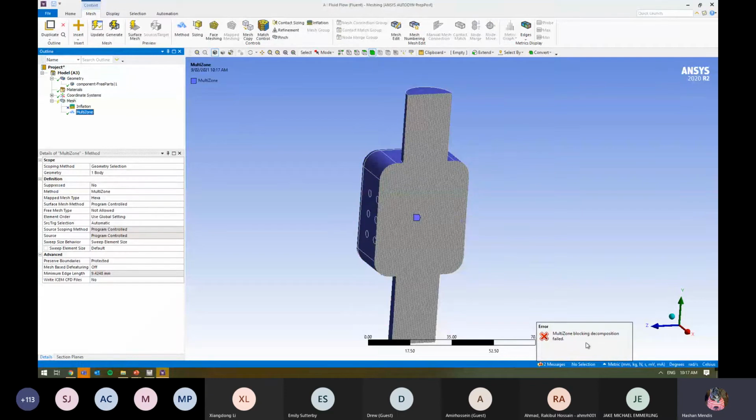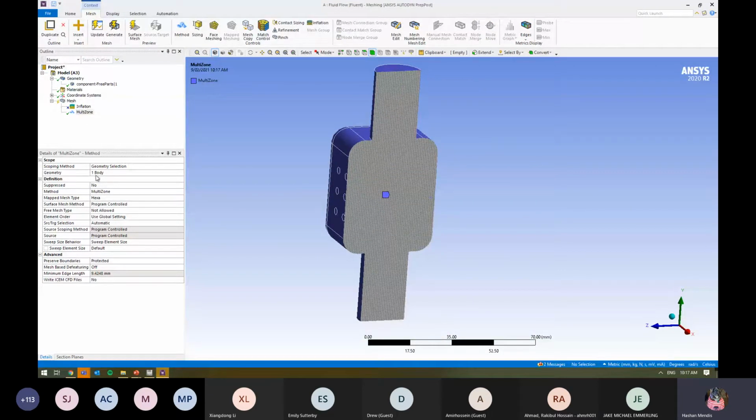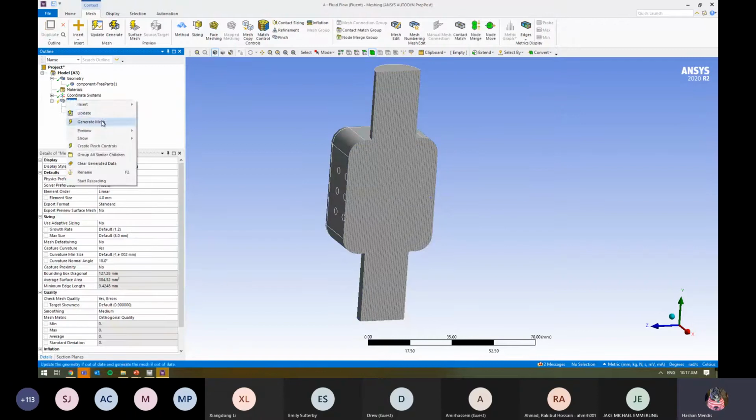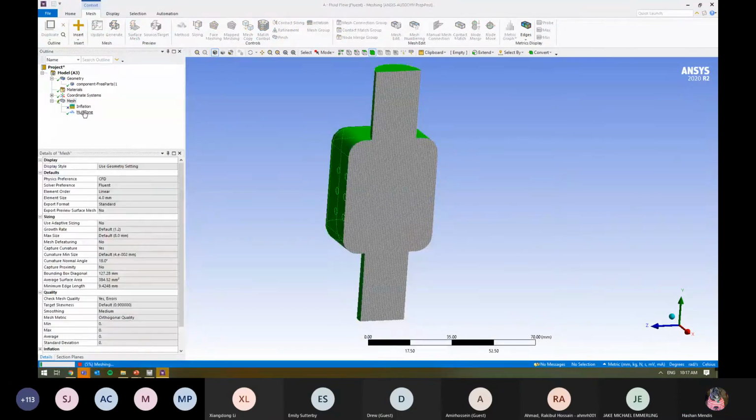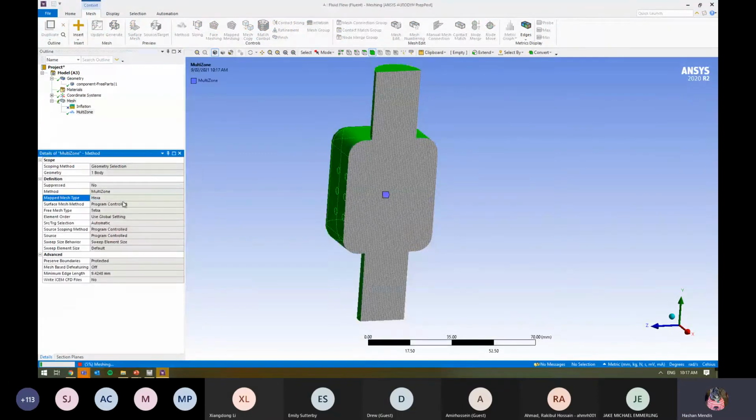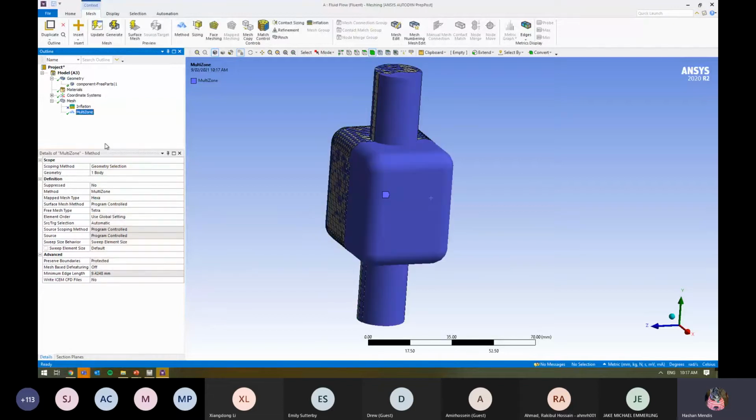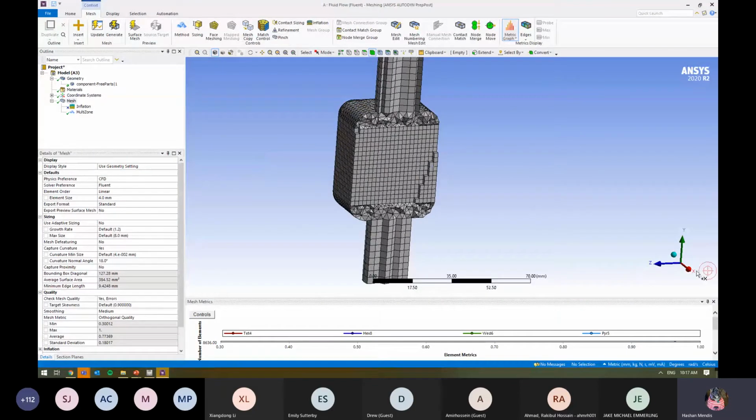Sometimes, you can see in this particular case, there are some problems and it doesn't allow you to actually do it. So the meshing tutorials, by the way, will go through this in a lot more detail. But what I might need to do is specify and tell it that, if you're having any problems, you can put tetrahedral elements where you need to. And you'll notice here, most of the mesh, we'll try to use as hex. These free mesh elements will be tets as needed, right?